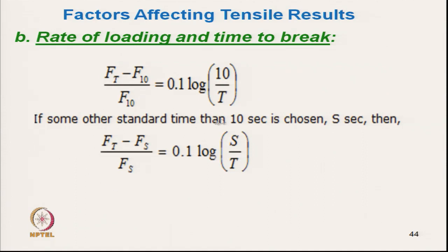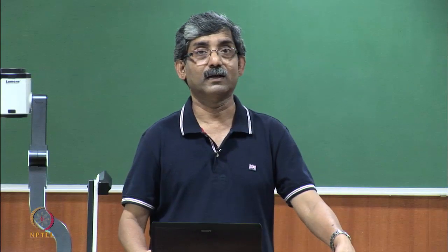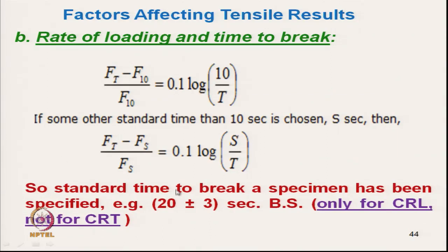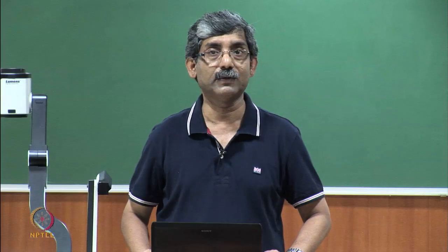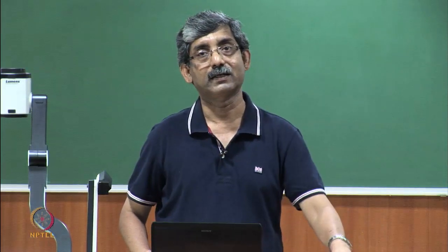Using this equation, we can solve different practical problems. Now, try to see the problem. The standard time to break a specimen as per the BS standard is 20 plus or minus 3 seconds. So we have to select the strain rate in such a fashion that the standard time is typically 20 seconds. Accordingly, we can decide.